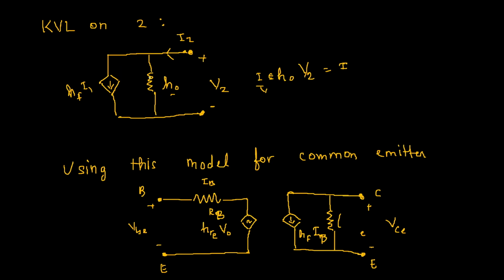We have an admittance here. This is not exactly a resistance, because this is something we are using to denote admittance. The part of the current which is dependent on V2 comes from here, and the part of the current which is dependent on I1 is denoted by a current dependent current source, which is denoted by this diamond shaped arrow. So I2 comprises both of these currents. One is dependent on I1 and the other on V2. This is how we draw the circuit on our output side.